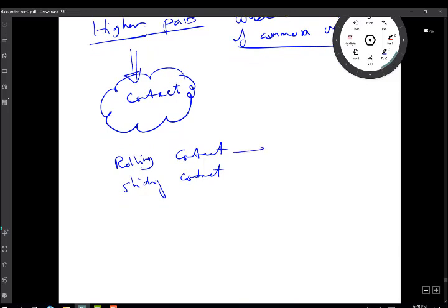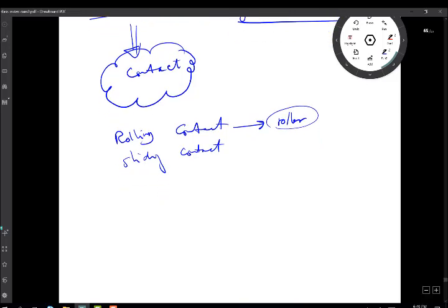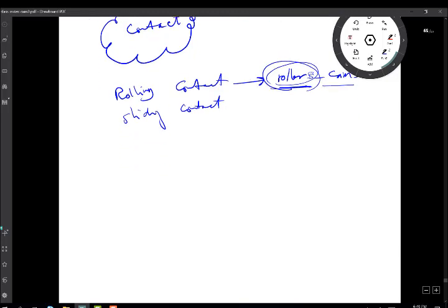If you use rollers, okay, but there is a condition for a contact to be rolling contact. Rollers in terms of cams, because we are going to see rollers and cams together. So if we have a roller, I straight away think of rolling contact, right? The rounded thing is manufactured in this way to produce rolling contact.